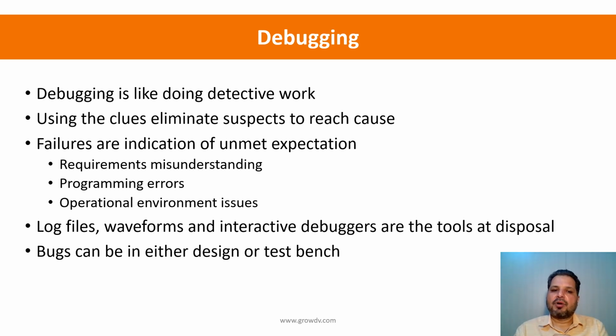And the process of debugging generally for the verification engineer starts with the log files. You look at the log file to understand what stimulus the test has generated, because for the constraint random test, the one key thing is that the stimulus generated will not remain fixed. Unlike directed test cases, where your stimulus generated is fixed in nature, so you can always correlate your test code to the log file, and they will all correlate one on one. But when you do the constraint random test simulation, you might have put a for loop, and inside that you are randomizing a particular scenario. What type of scenario it is going to generate is not defined.